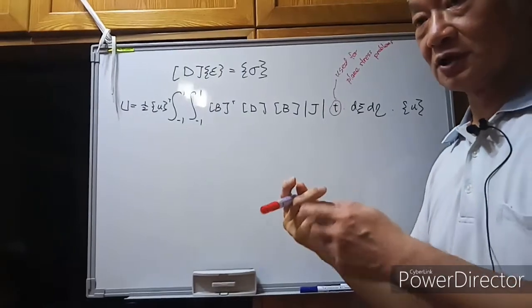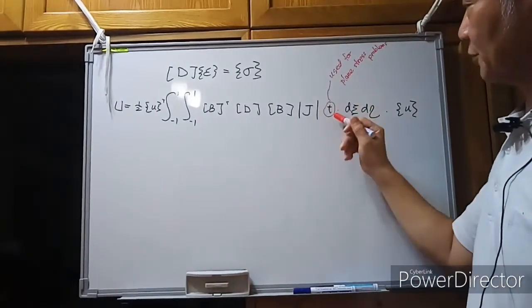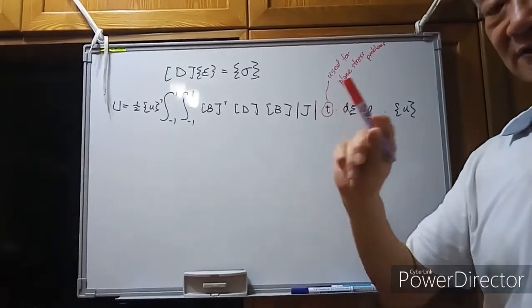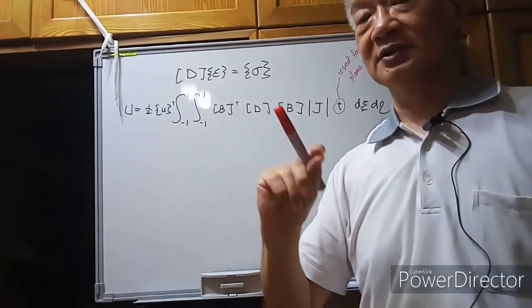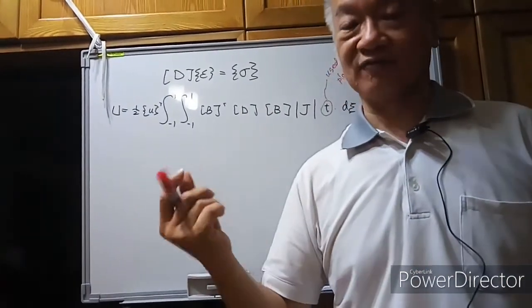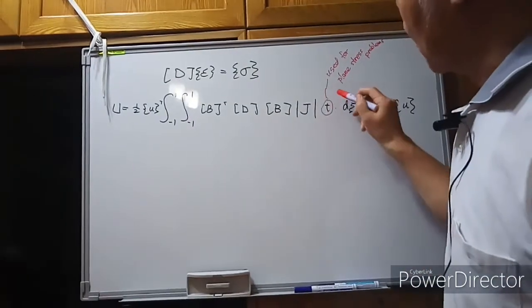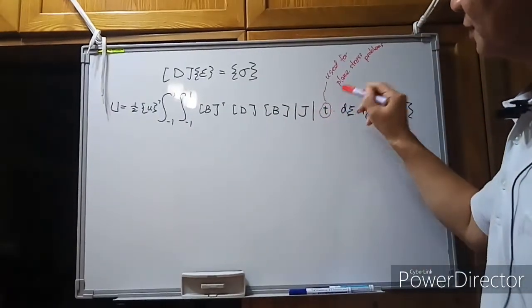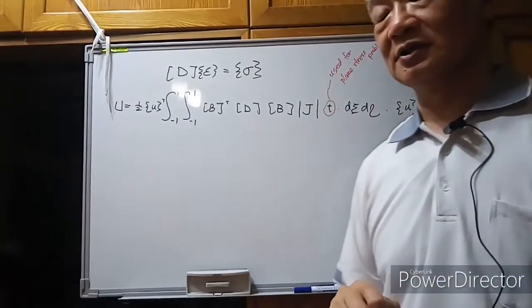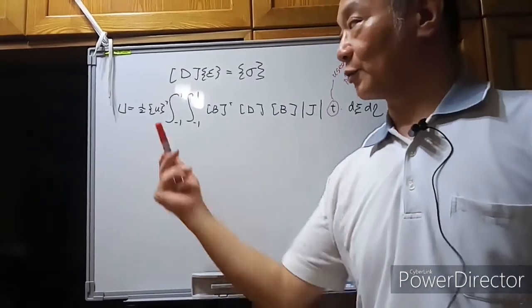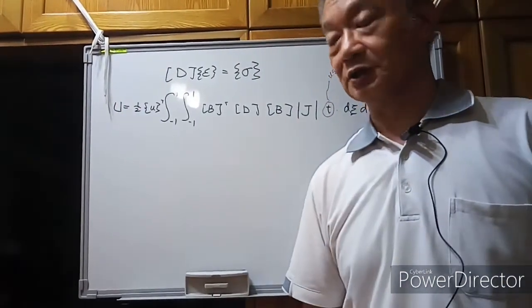It will give you the d area. And the d area times the thickness of the thin plate, then you can get the d volume. So for the plane stress problems, we need to multiply the t when we calculate the strain energy.